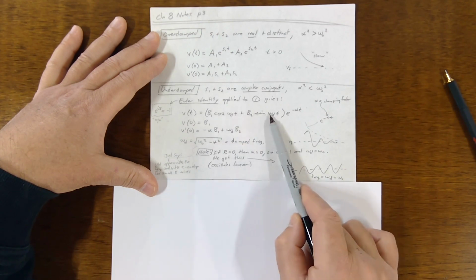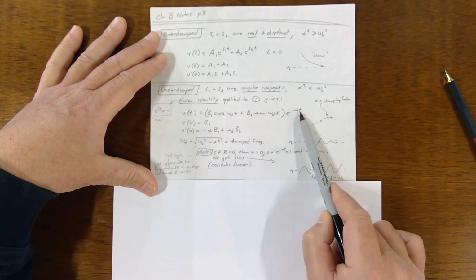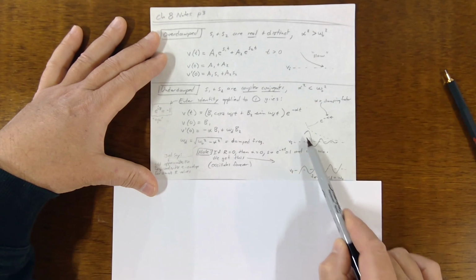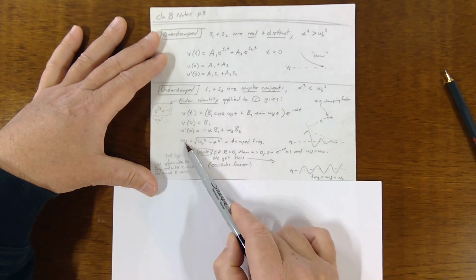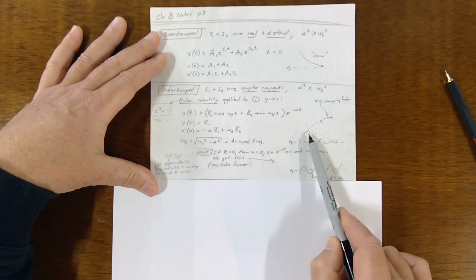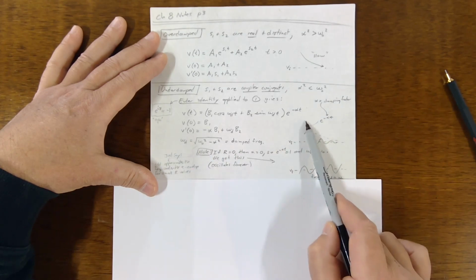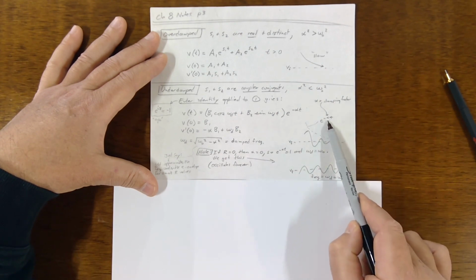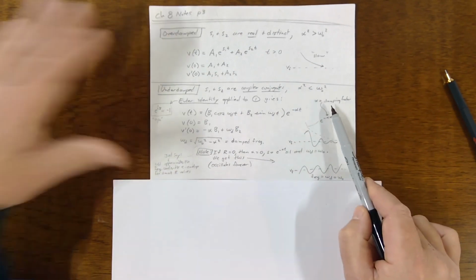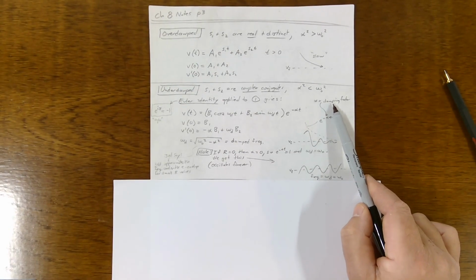But it's really just a single sine wave under an exponential decay envelope. That's what's shown over here. So you have this sine wave that's wiggling around at omega d, the damped frequency, okay? It's wiggling around, and it's underneath an exponential decay envelope, where alpha now, the same alpha, which was called the Neper frequency in the general solution,